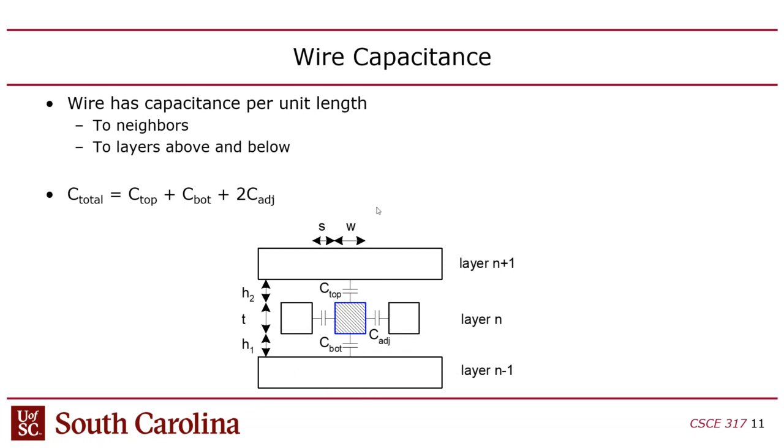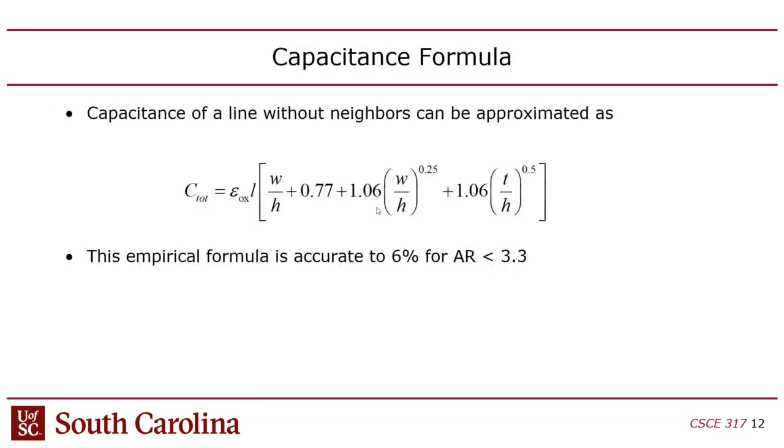So down the road, I think having to consider the capacitive effects of different types of packaging structures may be important. But anyway, the point is that the capacitance is determined by other conductors around the wire. So you would have to add all those up in order to get the capacitance of the wire.